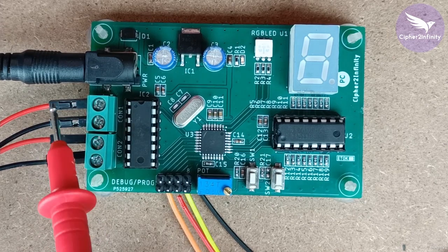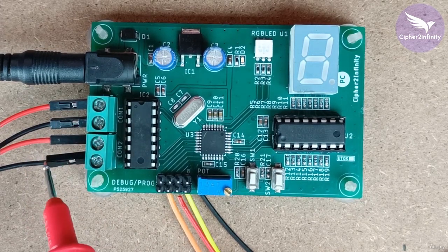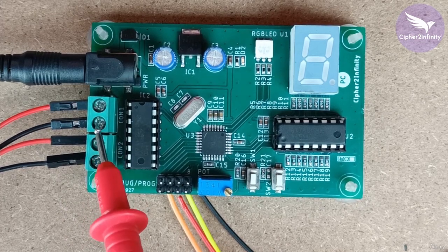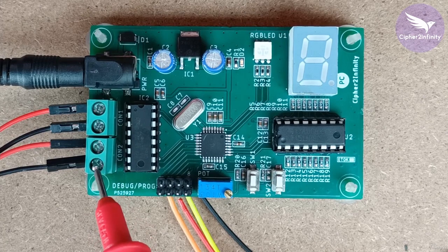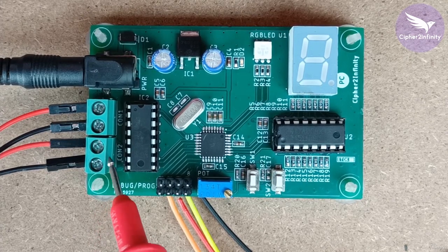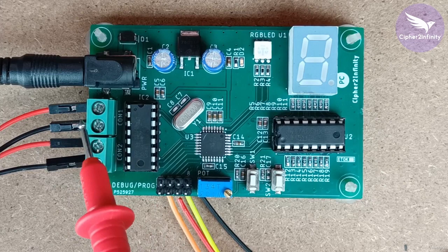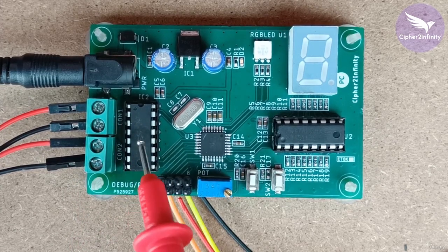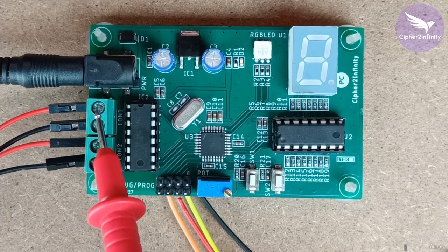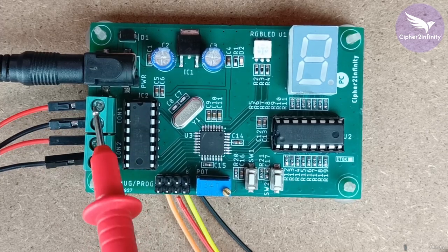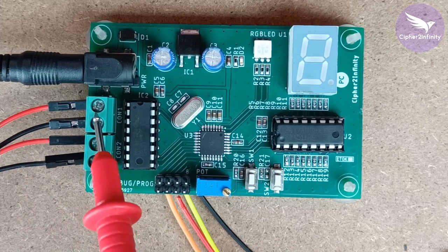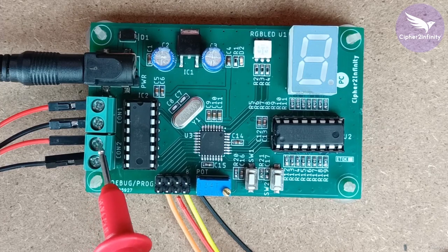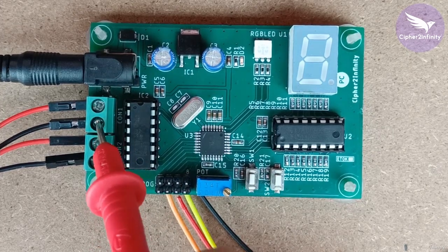So once you are sure both the motors are working perfectly fine, then there might be a problem with the connectors or these terminal blocks. So you have to make sure that the terminal blocks are properly soldered from the bottom side or not. Okay, so that could be the reason why your motors will not rotate. Okay, so if everything is fine with the IC, then definitely motors will rotate. Otherwise you will have to check the motors individually, or you have to check these terminal blocks whether they are soldered properly or not.